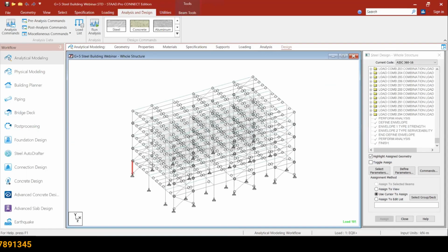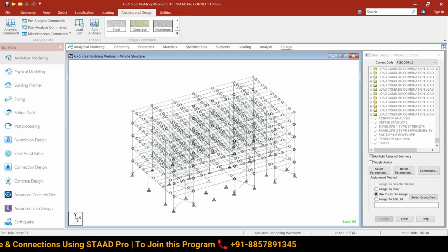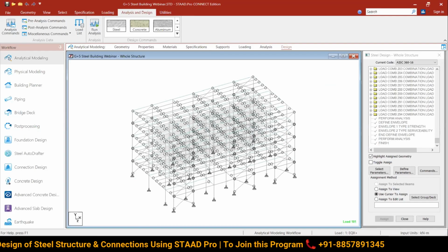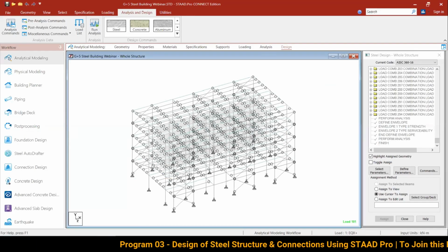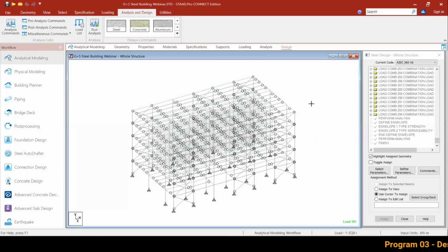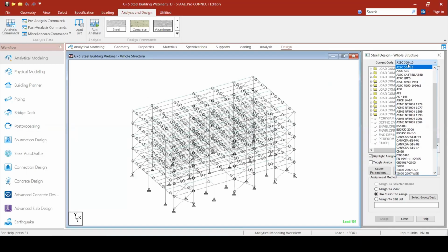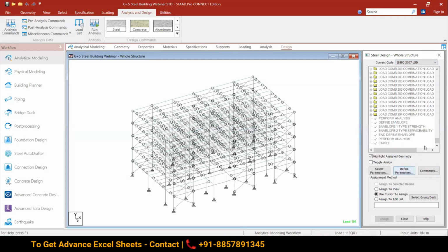and if you have this member somewhere in the middle, and if it is able to deflect in one direction, then in that direction you have to consider it as simply supported. And if in the other direction you have a wall or bracing, then in that direction the length will be different. Maybe in this case you won't be able to understand that properly, but if you have designed any steel warehouse or PEB structure, in that case it is much clearer.